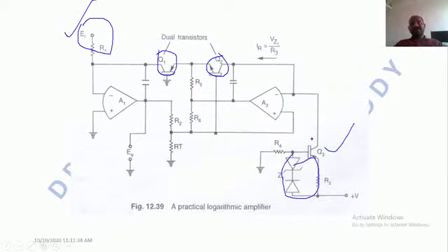Now, transistor Q3 means how much voltage. Here we are using the diode. What is that? Zener diode. Now here we are using the Zener diode. So the Zener diode in the forward bias acts as a normal diode, but in the reverse bias it acts as a stabilizer. Mainly the Zener diodes are used in the reverse bias, not in the forward bias, in order to avoid the fluctuations in the current. In stabilizers we are using the Zener diode, but we are not interested in elaborating the explanation related to the Zener diode.